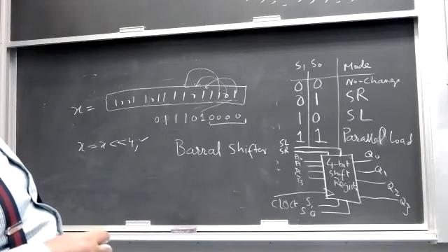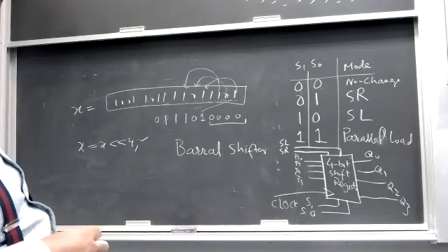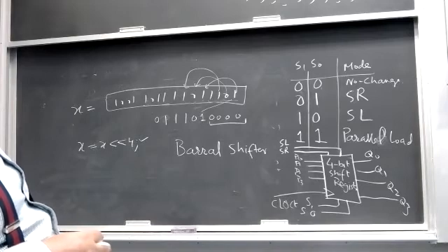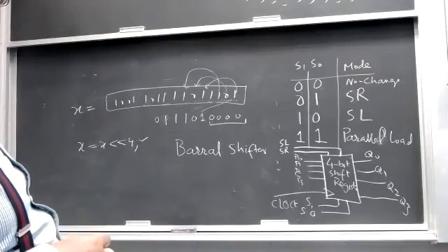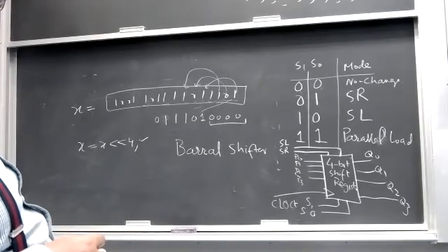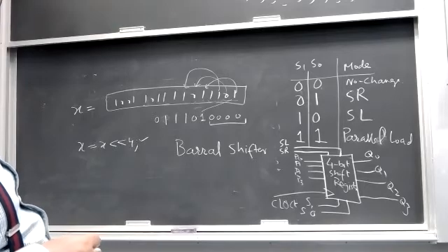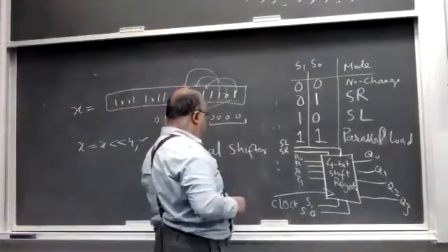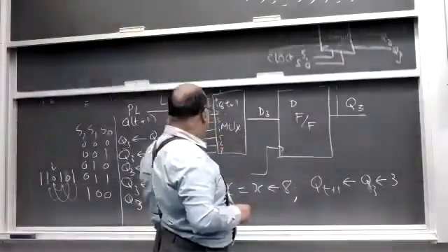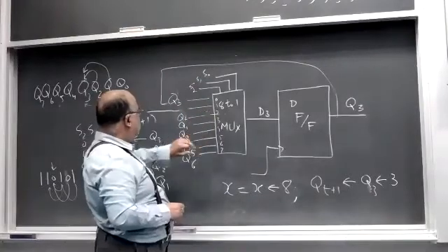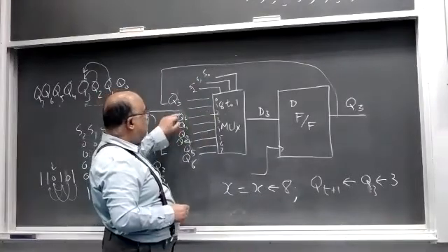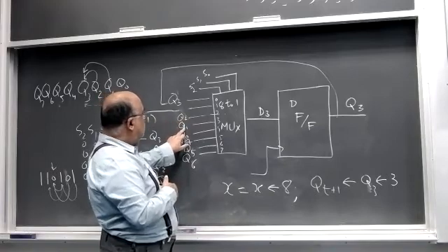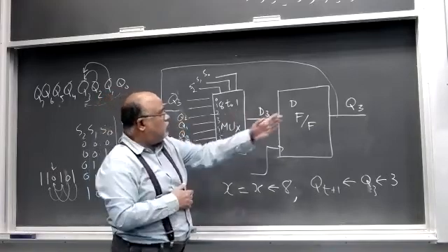Sir, in the 4-bit shifting circuit you made, why was it possible to shift left by 2? Was it possible? Would you have to have a bigger multiplexer? We made a bigger multiplexer, an 8-to-1 multiplexer. So 8-to-1 multiplexer. If Q2 comes instead of Q3, it will shift once. If instead of Q3, in the next clock cycle I put Q1, then what will happen?